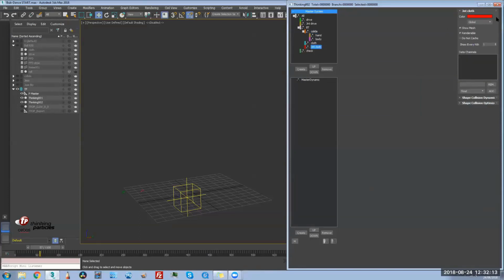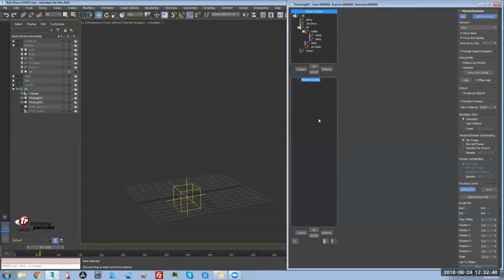For the joint cloth we want to have drops, because drops show you the speed of the object in the viewport in real time, so this is very useful. And cloth will be our actor. For the colliders we just want to see the mesh, so we don't want to see anything else. And joint will be ticks, and drive will be ticks as well. This is enough for now. You can change these parameters whenever you want, so don't be extremely precise.